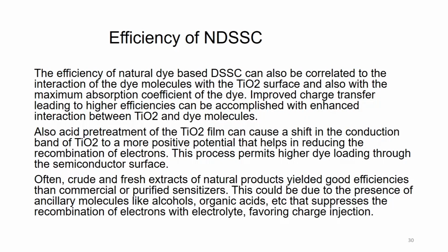The acid pretreatment of the titanium dioxide film can cause a shift in the conduction band of the titanium dioxide. Often crude and fresh extracts of natural products yielded better efficiency than commercial or purified sensitizers. This could be due to the presence of ancillary molecules like alcohol, organic acids, etc. that suppress the recombination of electrons with the electrolyte, favoring charge injection.